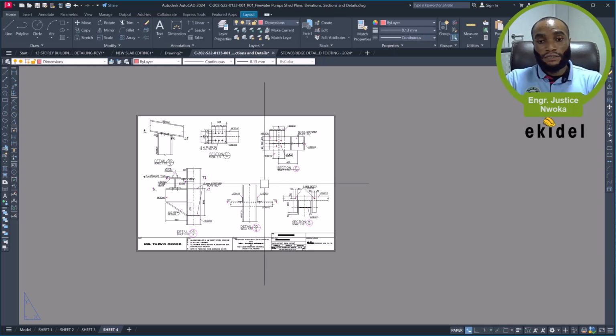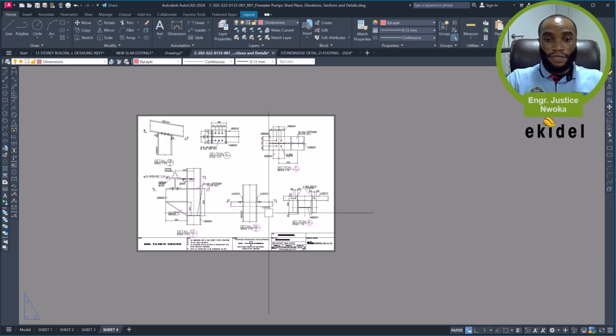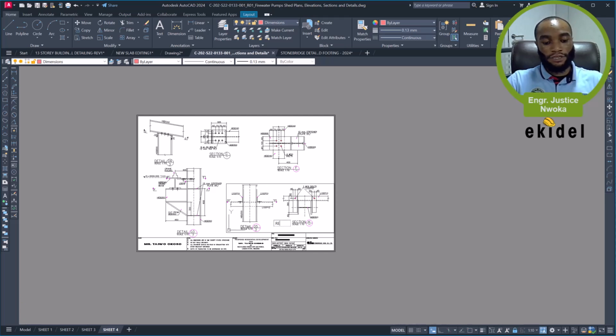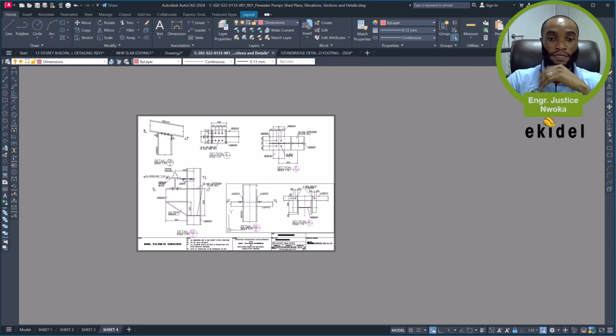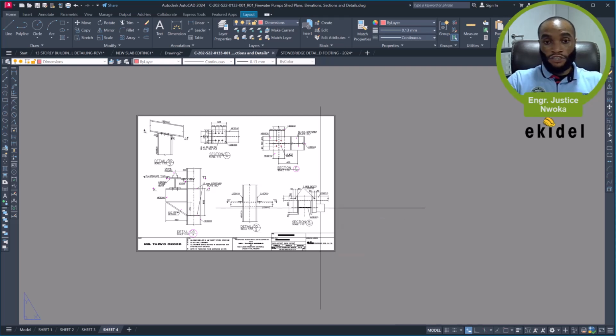I'll now come now, double click on this viewport here and type RE, okay, and then press the enter key. Okay, that's fine. Most times, yeah, that's changed, and now press PX. So even if you're hiding your listing, you can still locate where the viewport is and double click there. You'll be able to see the origin there, and press RE. Okay, and then that will change to that. Okay, black and white, and press PX.